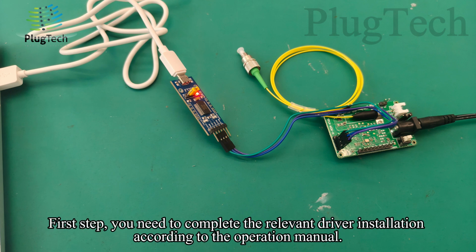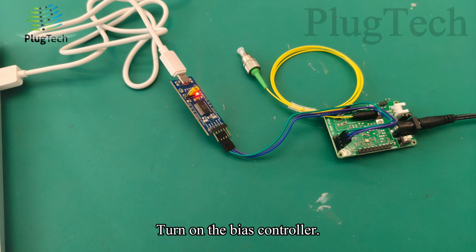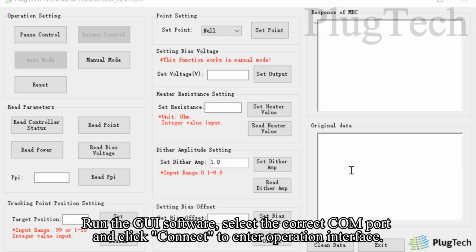First step, you need to complete the relevant driver installation according to the operation manual. Then connect the bias controller to the computer through a USB adapter board. Turn on the bias controller. Run the GUI software. Select the correct COM port and click Connect to enter the operation interface.